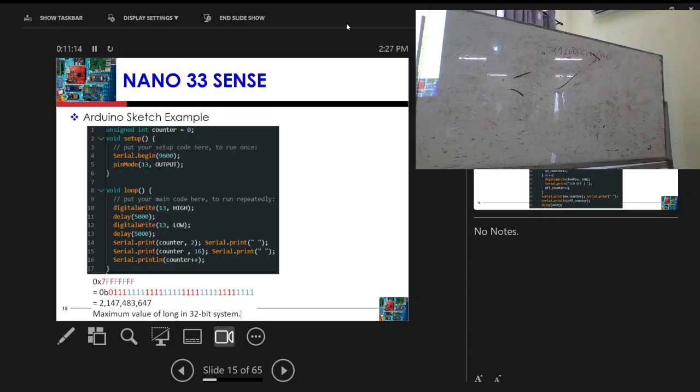So it prints the binary value of the counter. So if you don't bring the 2, what happens? If I do Serial.print counter without the 2, what happens? Why are you laughing? Computer engineers. If you don't bring anything, then you just print the counter. It prints decimal values. That is the default. But once you bring counter comma 2, then you print the binary value of the counter.